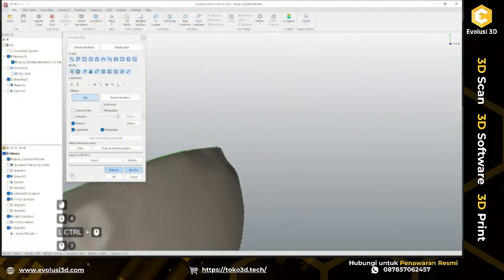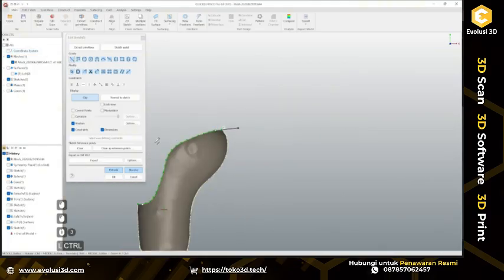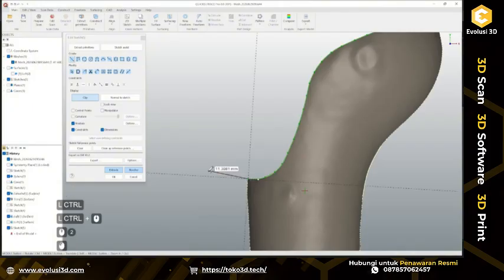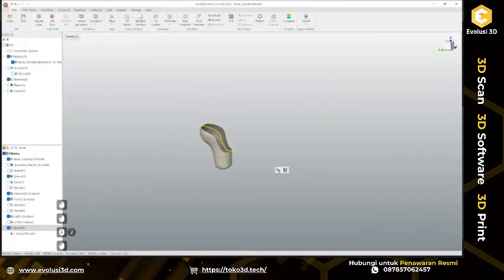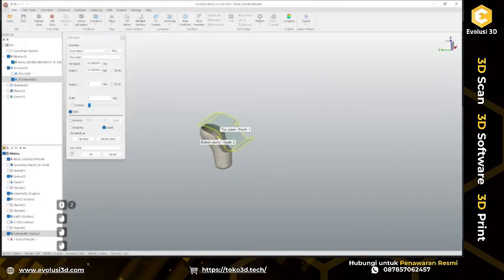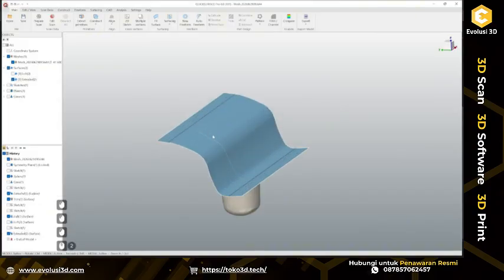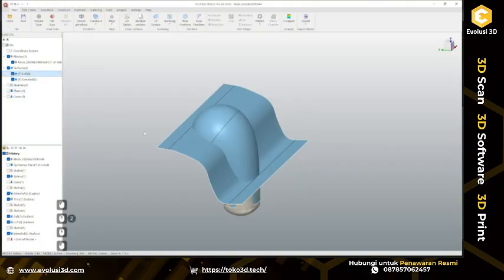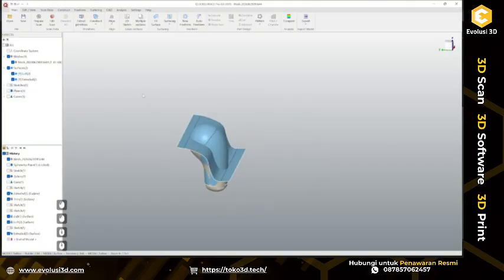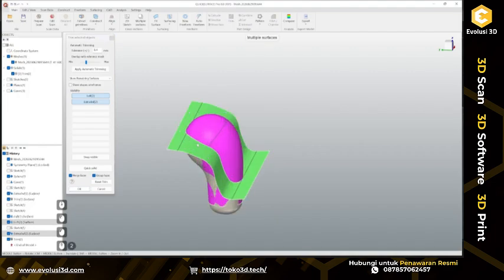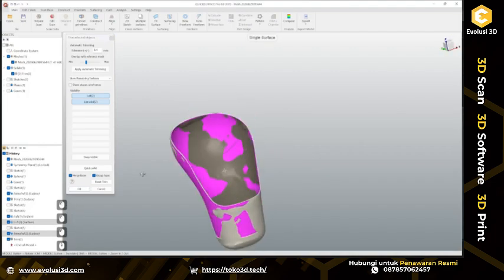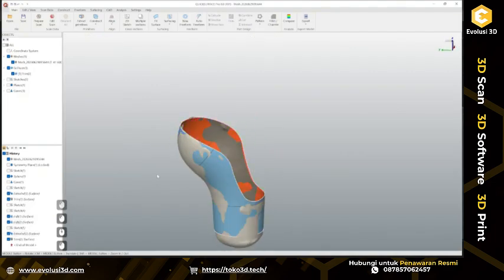Okay, top side looks good. Now I will just add some extension as straight lines, tangent to this curve. Now I'm just going to extrude all this surface, hide my lofted surface and trim all this to have a surface body.